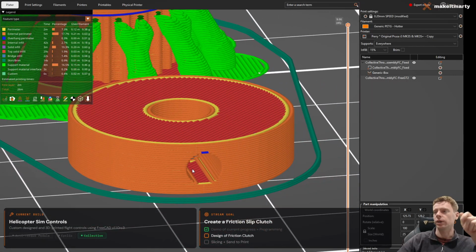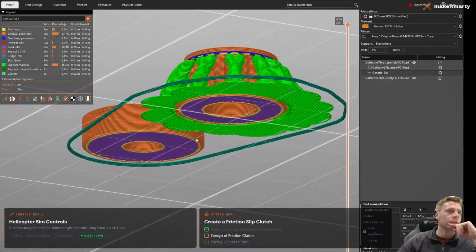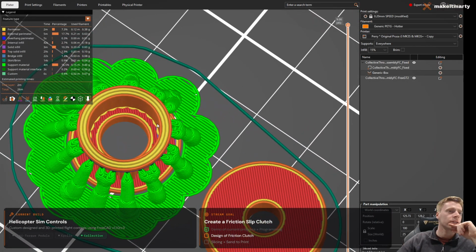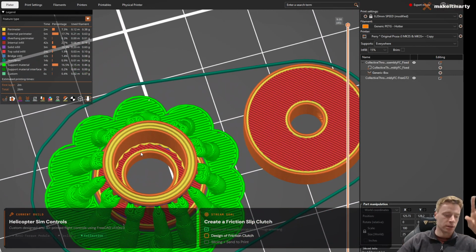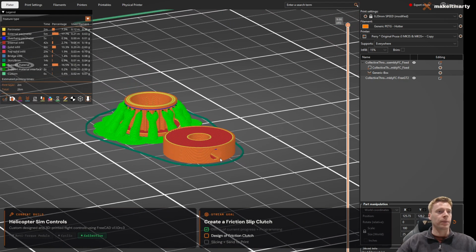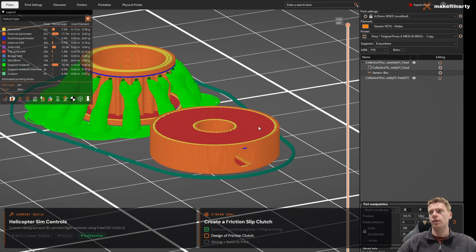It's fine, we're going to press fit that anyway, doesn't need it. And then we have our print there. So hopefully we'll be able to press the bearing straight into that. If not, we'll struggle. And then we can push a threaded insert into here, stick a felt pad onto here, and we should be good to go.